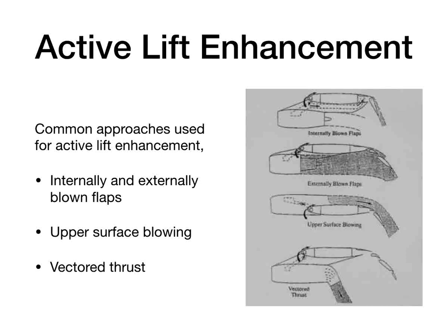For external blown flaps, the air is supplied by the engine exhaust and the engine is located below the wings. The flaps are slotted in this case so that high momentum air can reach the upper surface and energize the boundary layer over the flaps. A portion of the air in this arrangement is also deflected downwards.